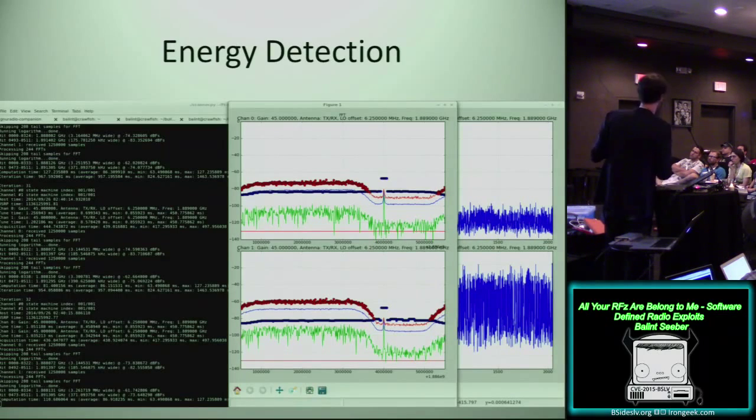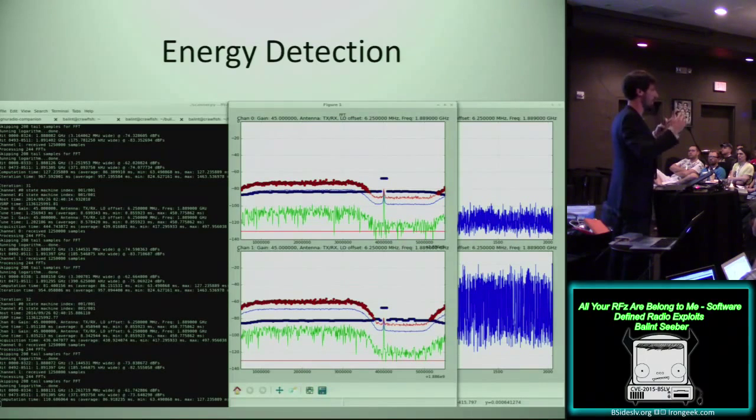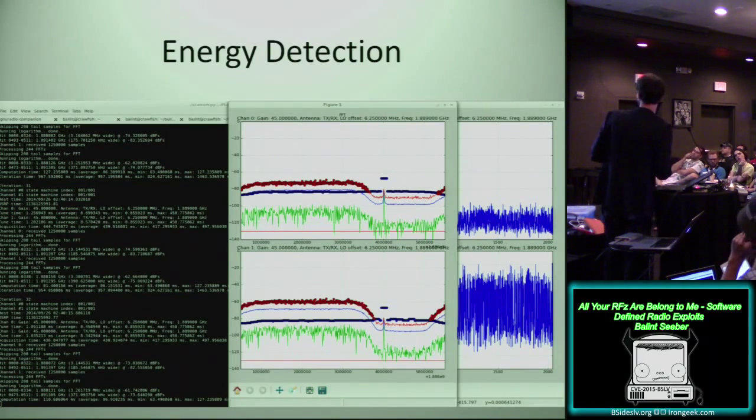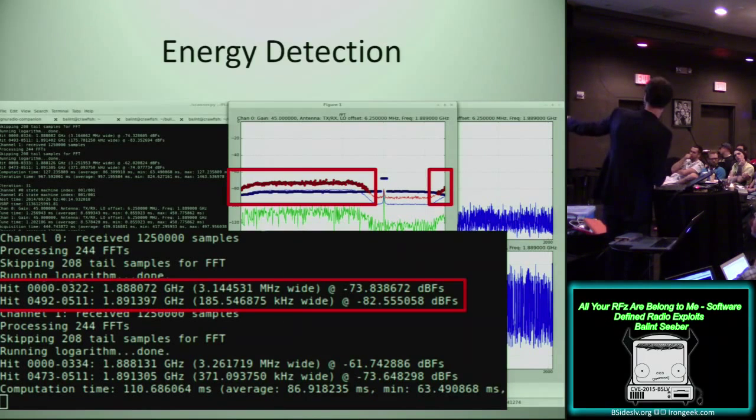And if you don't want to just capture absolutely everything, you can also do other tricky things like energy detection. So you might say, well, I want to capture the notion of my idle spectrum or a silent spectrum, and then any signal that pops up and exceeds some energy mask that I've defined here, in this case in blue, see how it's kind of flat, anything that exceeds that will be marked in red. Then you can see, hey, something's actually popped up, there's a signal there, I'm going to store that, and I'm going to analyze it later. And when it actually detected those signals, you can see that it found this hit there, and it stored that information, so you can process that for later.